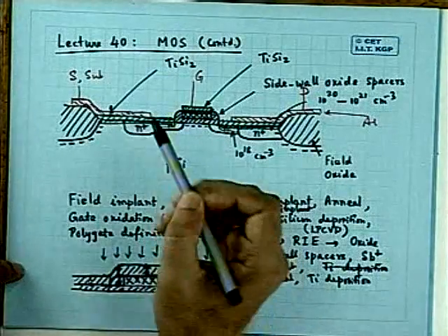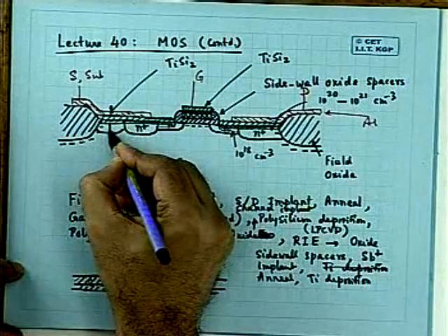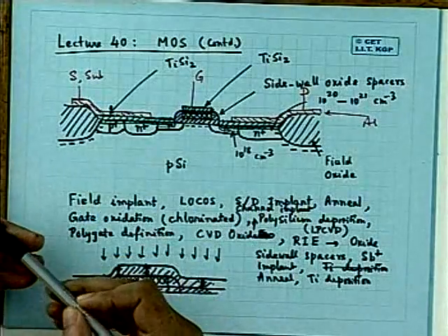Now, you have understood the basic technology for making an IC, for making a MOSFET. The substrate and this layer are directly connected. Sometimes, which I have normally done, here I just forgot to tell you: there is a boron implantation here also. Usually, a boron implantation is made for a good contact, which I forgot to tell you. So many masks are there. It may typically be a 12 to 18 mask process. Though the simple technology may require only 6 masks, many things are added. As a result, the number of masks, the photolithography steps, is quite large today. Therefore, we have to do everything as best as possible by self-aligning techniques. I'm not going into the technology because otherwise it will consume the whole class.